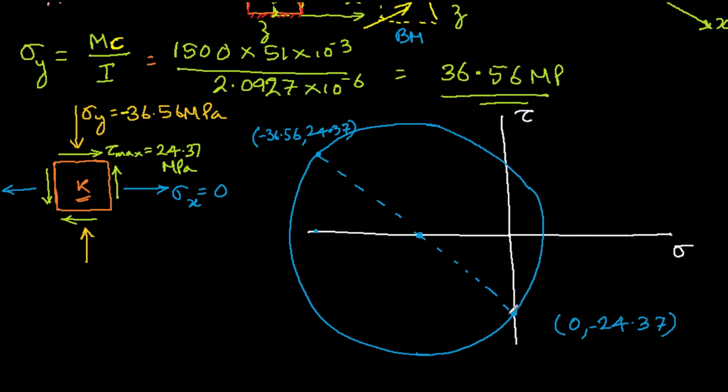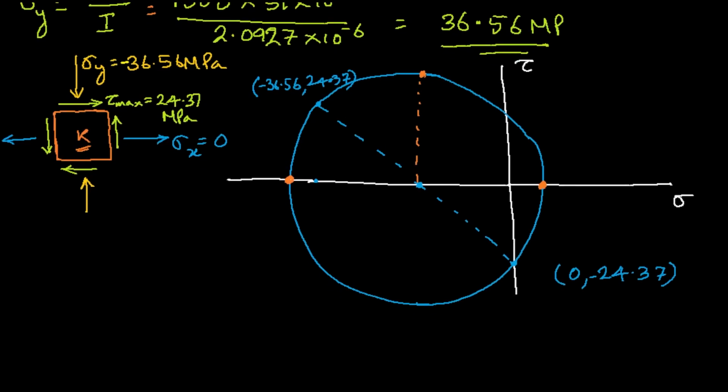Fine. So we are now concerned with which points? These are the points. This is one of the points where the principal stress exists because the shear stress is 0, and this point at the top. So these are the points which we want to evaluate. Either you can draw this Mohr circle to scale and measure them from the diagram, or else you can calculate them using the formula. How to get that? This point is the sigma average, so let's calculate that.